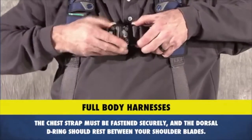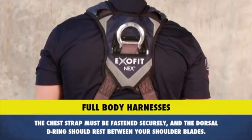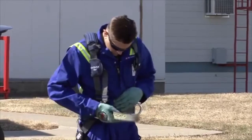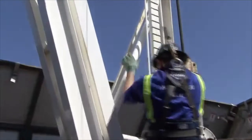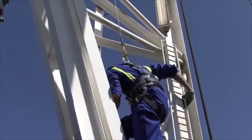The chest strap must be fastened securely, and the dorsal D-ring should rest between your shoulder blades. Once your full body harness is properly fitted, you'll get freedom of movement, comfort, and maximum protection in a fall.